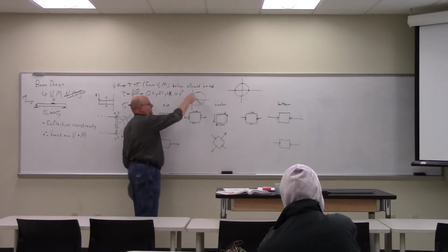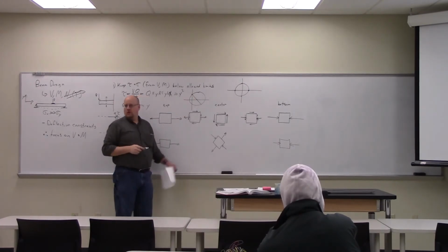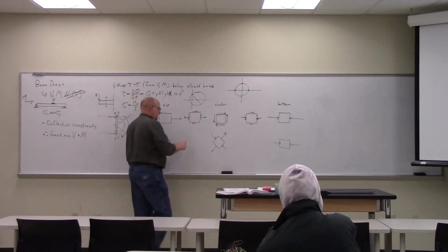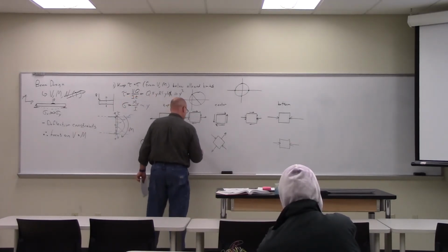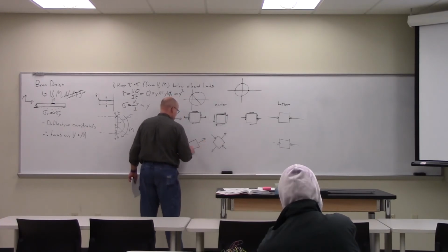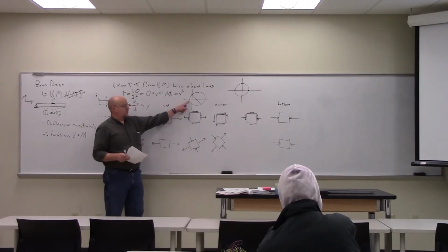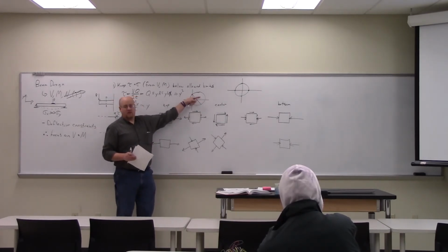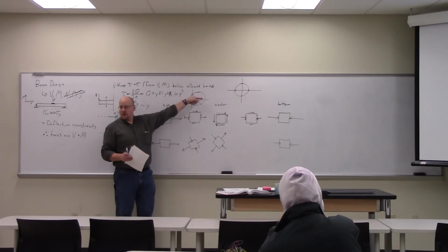But my shear stress has some value. So that's where I stand on this one. Everybody see that? So if I were to draw this principal stress, it would be a small compressive stress, a large tensile stress, and a rotation of less than 45 degrees. A rotation of 2 theta p of less than 90.